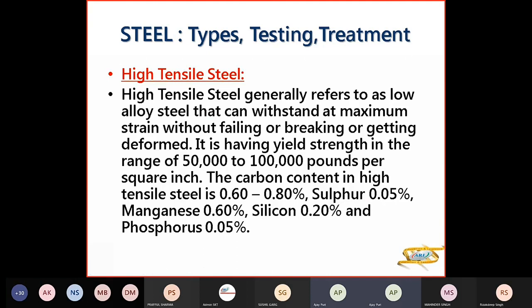Now, in certain areas on ships where you have high stresses or where you hog and sag a lot, that is your garboard strake, your keel plate, your shear strake, regions where you have very high tensile stresses, which is a hog and sag, there you have fittings of high tensile steel.